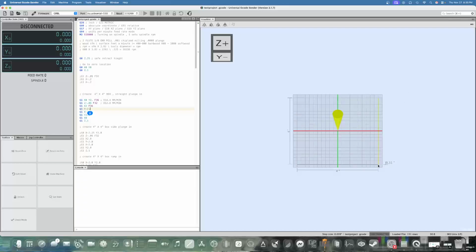And then the same thing for the X. We go from +2 on the X to -2, which is a 4-inch travel. Y is going from -2 to +2 with a 4-inch travel. And since this was started with X in the center, it's told back over to X. You can see that line highlighted right here. And of course, Z comes up and clears the part, 100,000. That would be, I guess, a 60 thousandths deep contour for where you're going around.